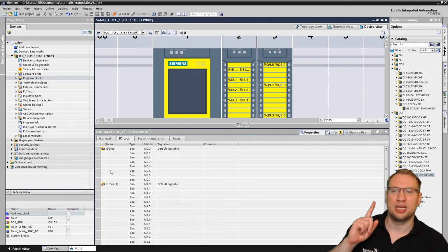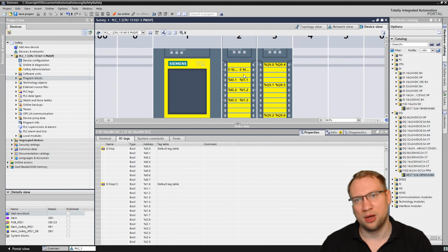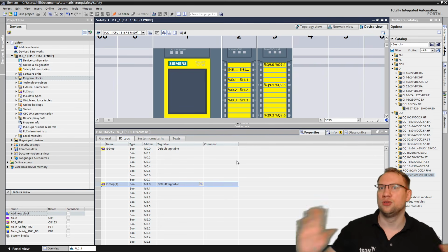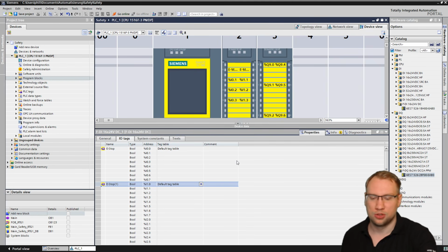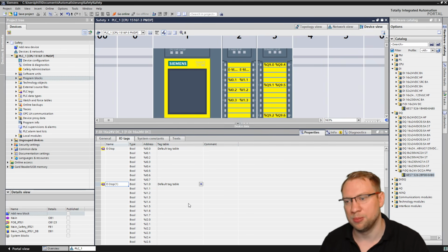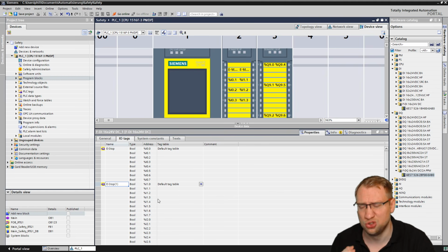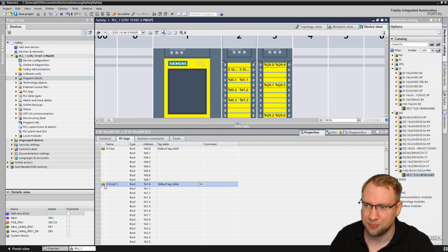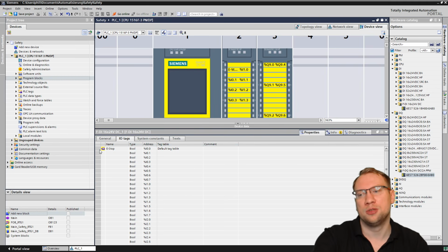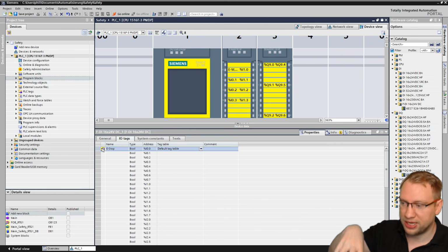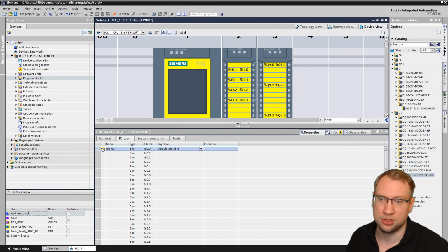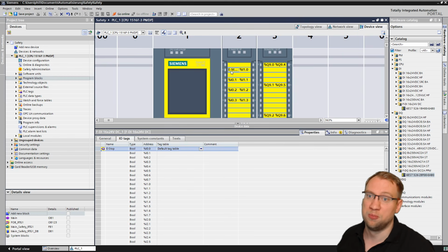Right now, because I have set these two to 1 out of 2 evaluation, the second one here doesn't do anything. Always the lower channel is responsible for both. So if I use this in my program, I will have many errors because it doesn't do anything. So get rid of this. A 1 out of 2 evaluation means both of them work together on the lower channel. So in our case, I00. Right? This one is responsible for both of them.